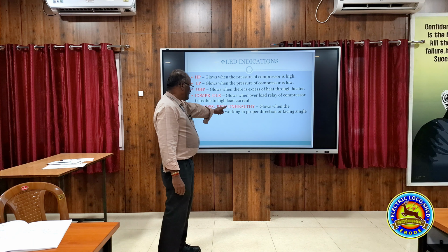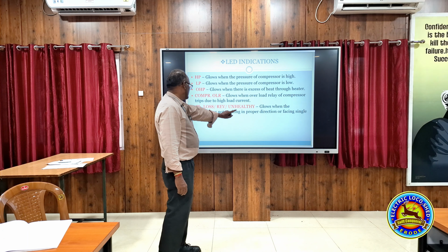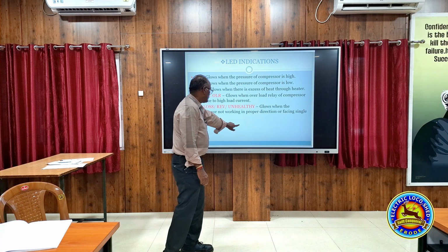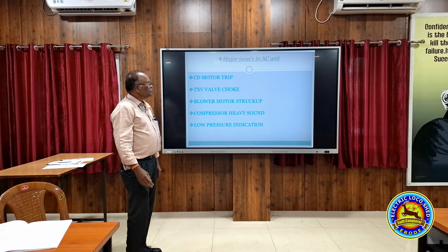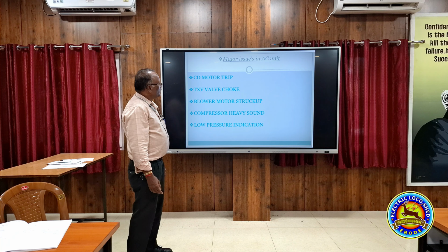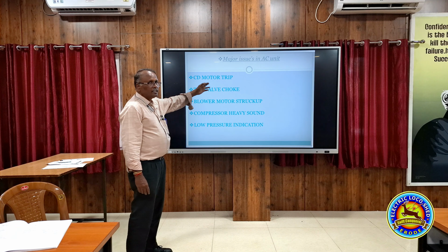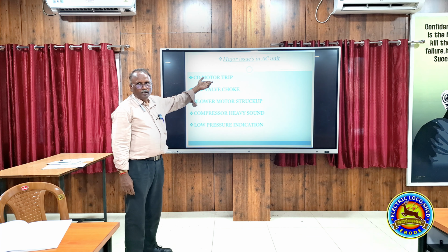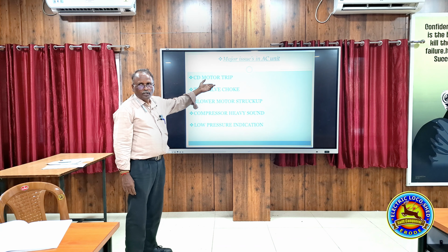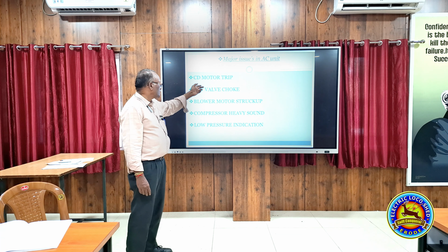Phase sequence relay healthy glows when the compressor is not working in the proper direction or facing single phase. What problems have we faced? Major issues are the CD motor tripped, CD motor IR is zero, CD motor stuck up, CD motor bearing unusual sound. Like that, various defects we have faced in the CD motor, that is the condenser motor.